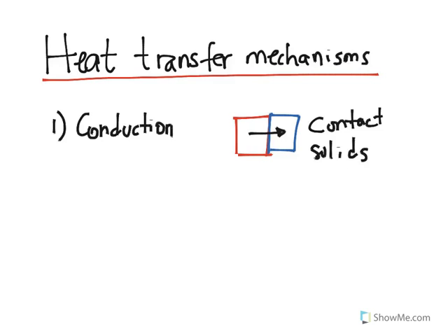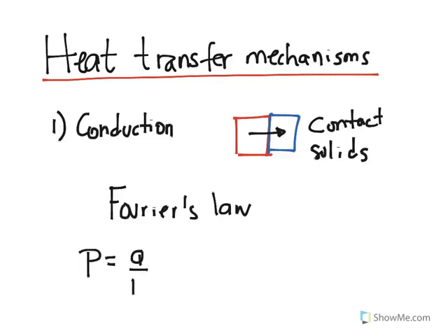This is defined by the so-called Fourier's law. Fourier's law states that the rate of transfer, which is for instance the thermal power, heat over time, is going to be equal to minus k, which is the conductivity, and this is dependent on the system, times the area, the transverse area, times the change in temperature due to a surface.